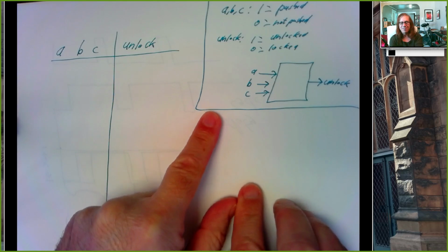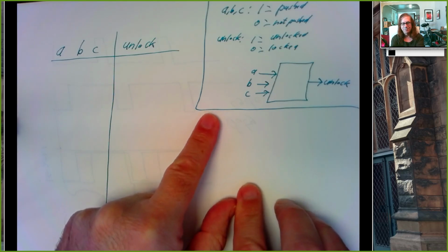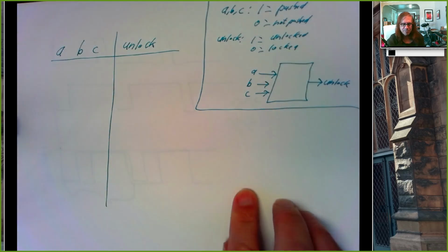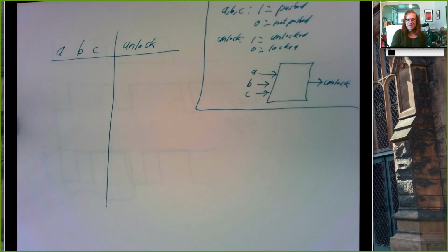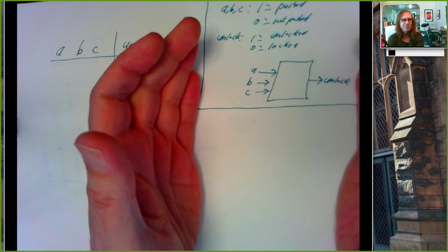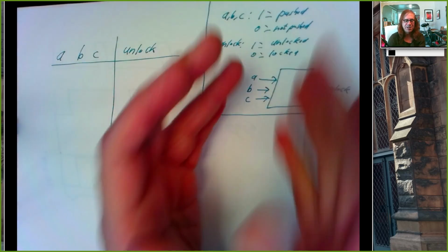Whatever buttons you have, when the button is pushed, we're assuming that generates a logic 1. If your push buttons generate a 0 when they get pushed, you need to do something to make it work with this kind of circuit, or you need someone to design a different circuit where 1 means not pushed, 0 means pushed, and so on. But this is just the top level view. What goes in, what goes out, what do they mean?